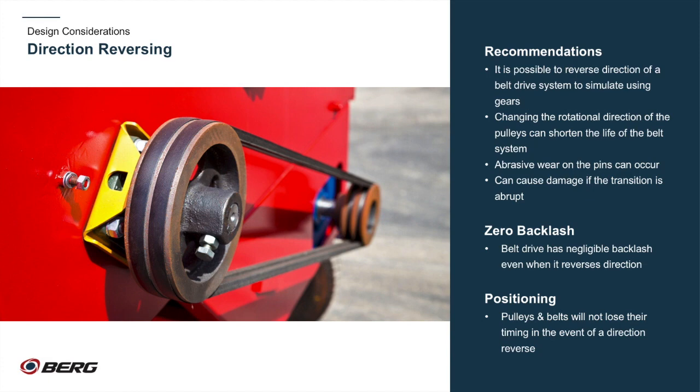Because of this, the output rotational position can be very closely held relative to the input position in cases where this is important. However, using the belts in a direction reversing manner will require additional guides to ensure proper operation and will likely shorten the life of the belt system.